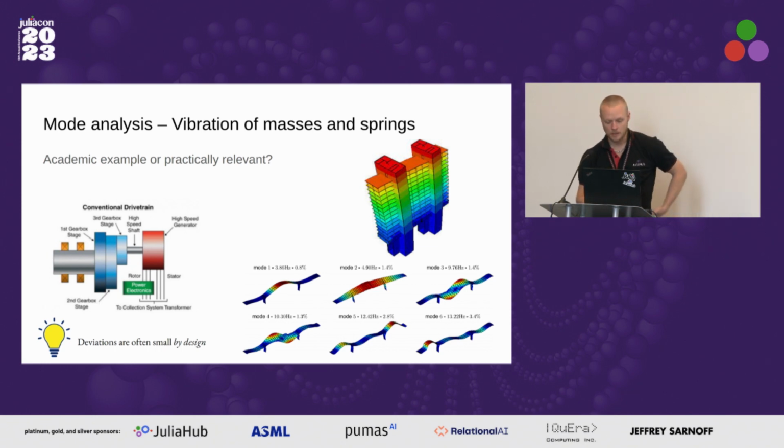We can also do this for a bridge. So we have a bridge in the bottom right there. And if we think of a bridge as a kind of flexible structure, that will also flex in the wind and as trucks pass over it and so on. And it might be able to flex in many different patterns. These patterns, we call them modes, and they have certain shapes. So maybe it will flex up and down, or maybe it will flex a bit like this and so on.